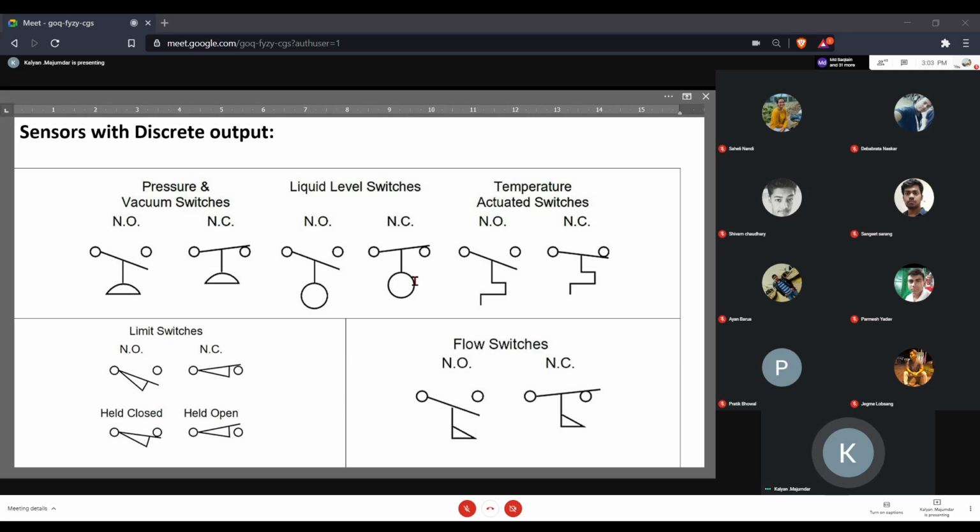Again, it turns on. So there must be some kind of a switch inside the refrigerator which is sensing the temperature inside your refrigerator. And that in turn controls the operation of the compressor, which basically is driven by a motor. I mean, it drives a motor and the motor in turn drives a compressor. So there's a temperature switch inside your refrigerator. There's a temperature switch inside your air conditioner which senses temperature, which is activated by temperature.